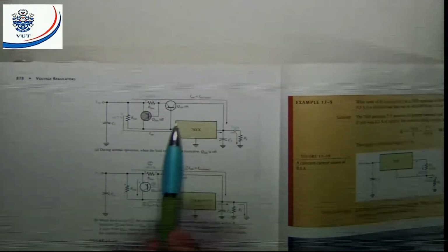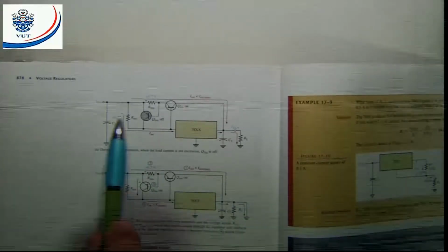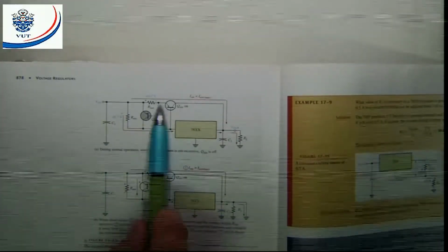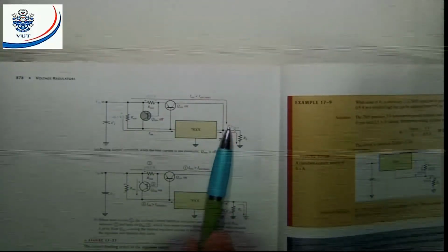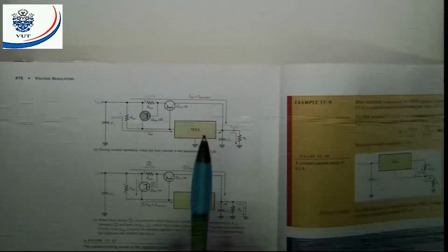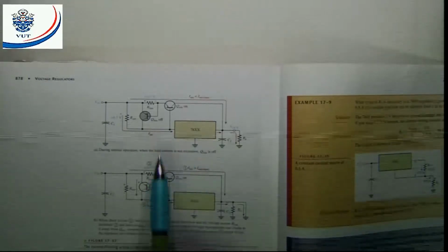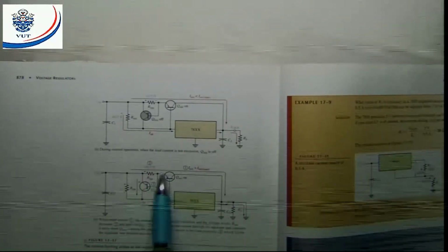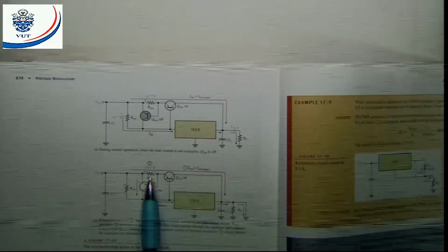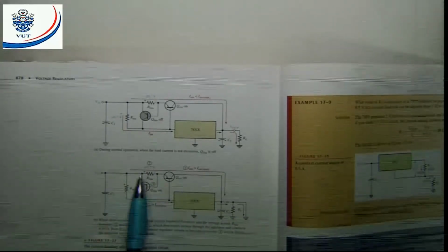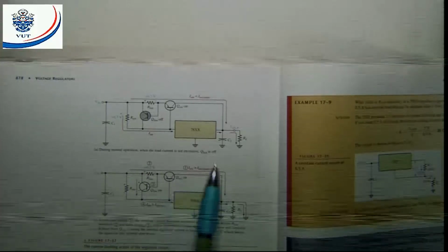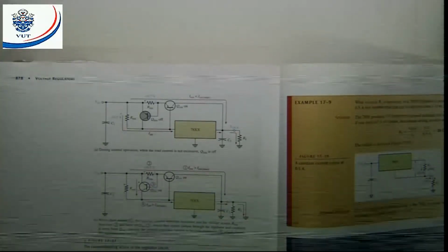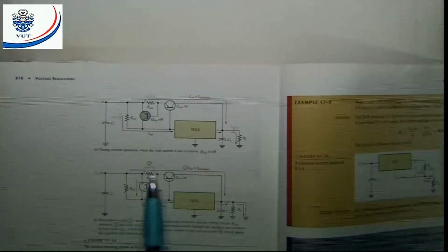There will be a certain amount of current flowing through there, and that transistor will be on, and there will be current flow through that transistor as well. But the moment that volt drop becomes 0.7 volt or larger, what will happen? I will start doing the current limiting, and this current can't increase anymore due to the current limiting circuit here.